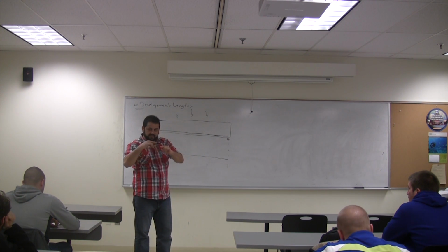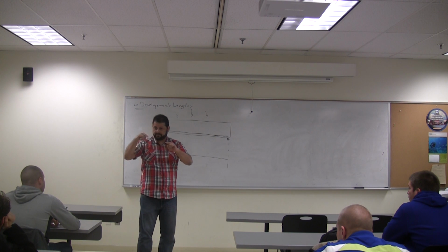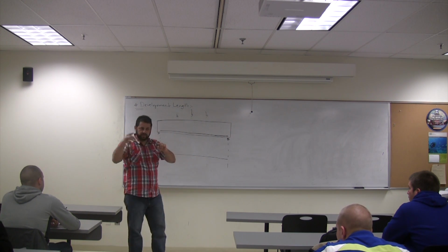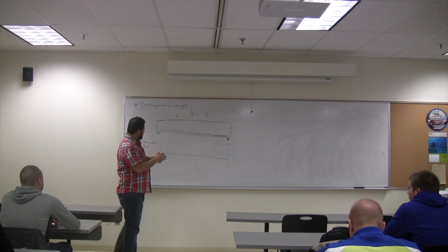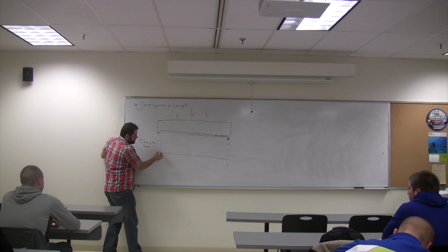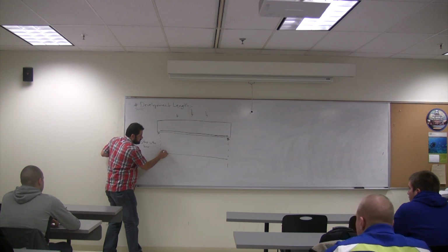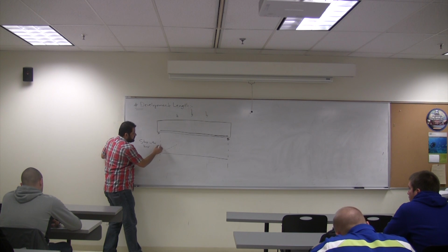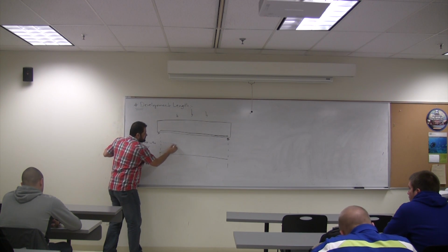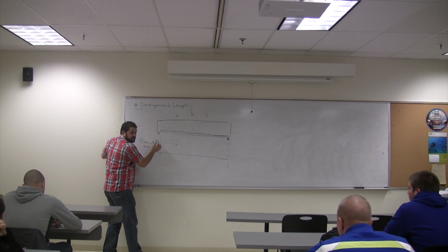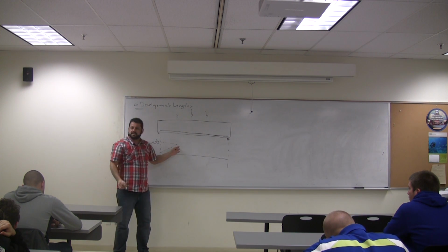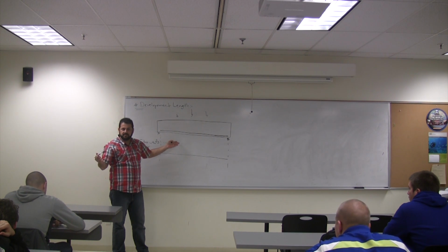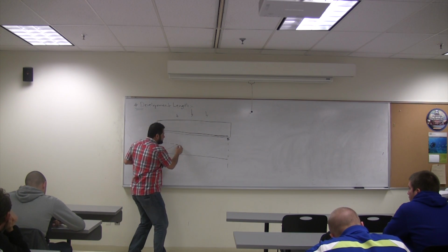So the bar now starts developing tension. Tensile stress through the bond with the concrete. Right? So the stress, I'm saying, will keep increasing as we go. Once you hit Fy, can the bar develop more stress, a stress larger than Fy? No, that's the yield. So the stress will be constant.